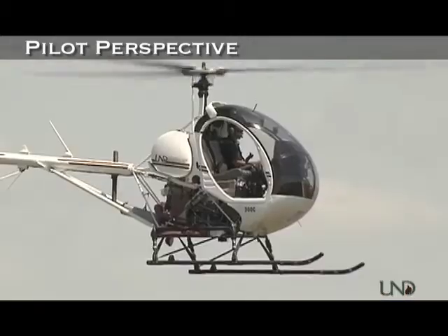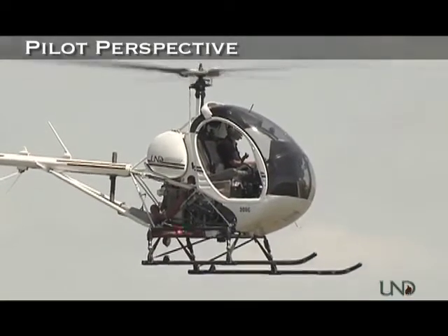Once a pilot has his clearance to air taxi, you're going to start off by doing a normal takeoff into the wind. Once you get going above ETL, basically somewhere around 16 or 24 knots, you're just going to continue at that speed at an altitude anywhere from the surface up to 100 feet. Generally, we cruise at around 25 feet and somewhere around 20 knots, just to maintain a safe airspeed and altitude combination. ETL stands for Effective Translational Lift.